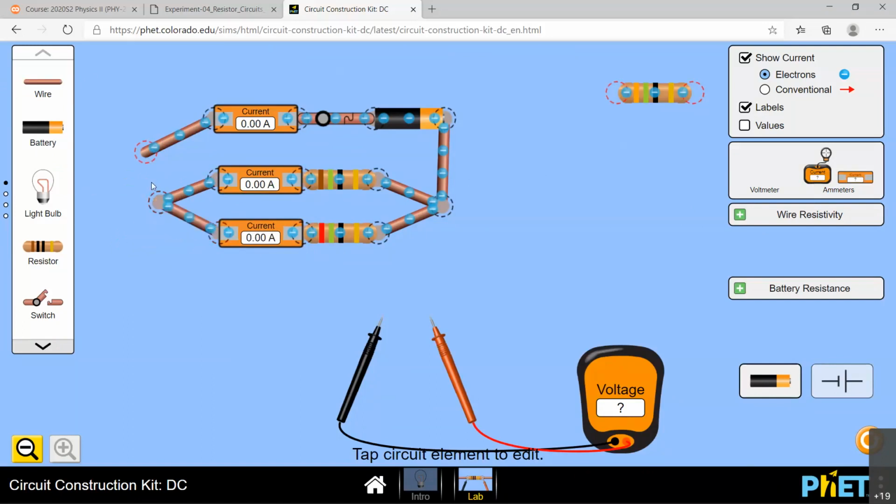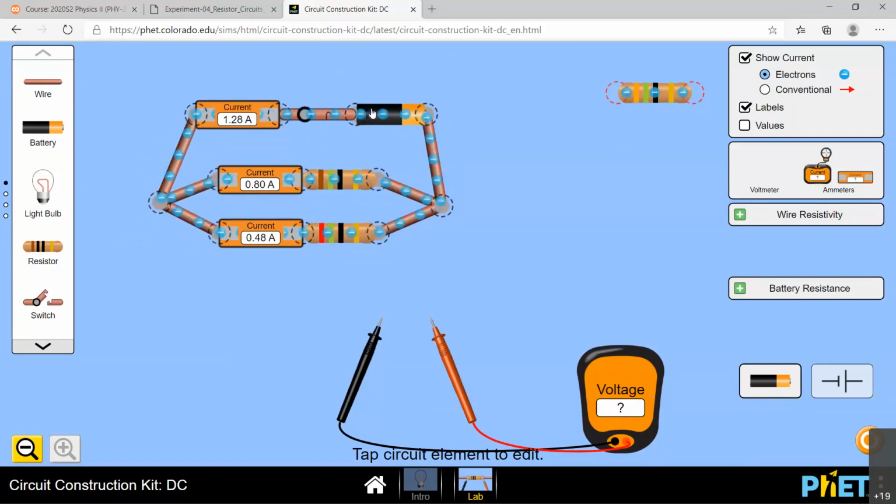Okay, now we have the same circuit again like earlier. Now you can see ammeters. I actually put 3 ammeters now, right? Because it's a simulator, we can have any number of items as we wish. But if this is an in-class experiment, you can't actually have 3 ammeters. Each time you have to break this point right here and then put the ammeter. The ammeter should go serially, right? That will tell you the current. And the voltmeter can go parallelly.